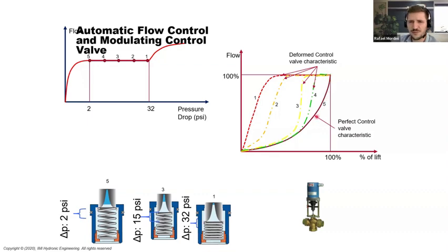The authority is 1, so you can control your modulating with no issues. But as we start to look at the other terminal units that we may have closer to the pump, you will notice that the pressure drop across the valve increases, right? It's easy. We have the 2 PT ports on an automatic flow control valve. You just measure there. Let's say that you have 20 psi, right? So 20 psi would be something around this 0.3 here.